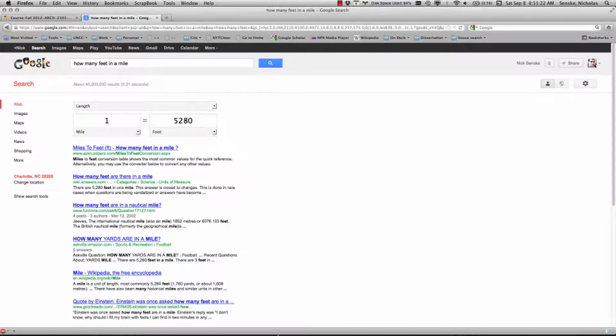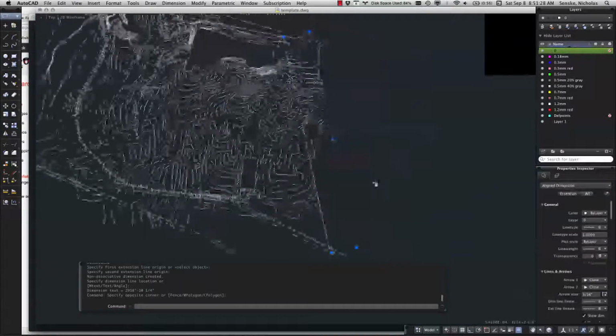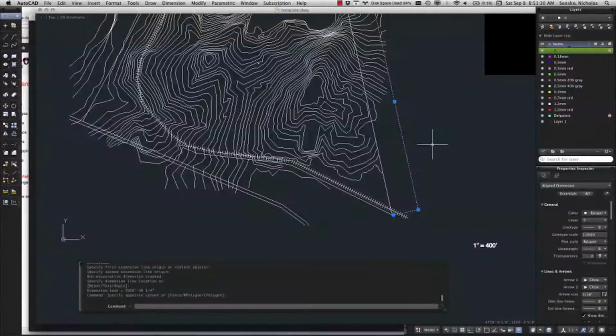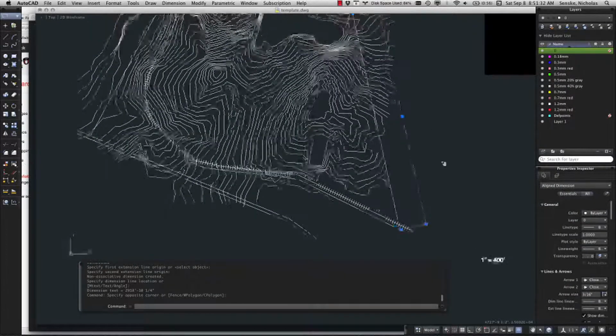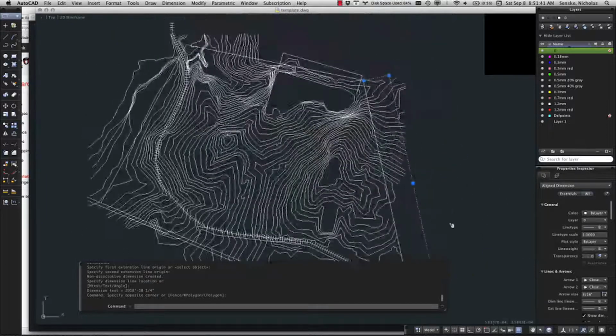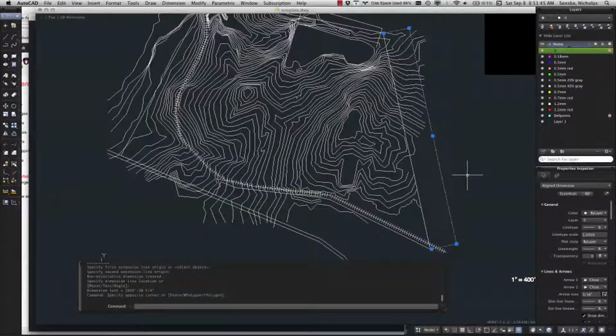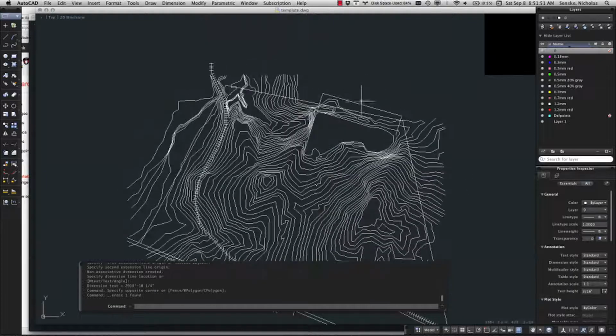So that seems plausible, and what we did should be right. If 1 inch equals 400 feet, then multiplying it by 12, for 12 inches in a foot, ought to convert that units to feet. Okay, so yeah, I think intuitively that's pretty good. I think it's about a little more than a half mile across. Not too bad, okay?